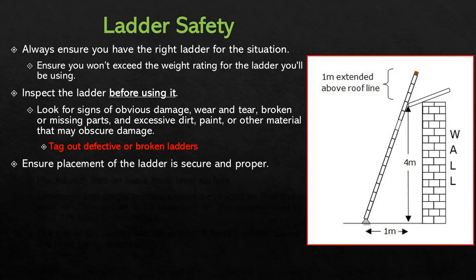Ensure the placement of the ladder is secure and proper. What this means is that the feet of a ladder, whether it's an extension ladder or a step ladder, or even an A-frame ladder, need to be on the same level and on a level surface. There are some ladders that are specifically designed for uneven surfaces where the left side and the right side can be uneven, but most ladders are not designed for that. If you have them on uneven surfaces, the ladder is not going to be straight. And as you climb the ladder and get further from the ground, the chances of the ladder falling to the left or right and taking you with it are greatly increased.